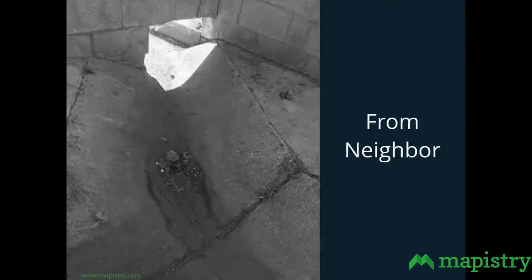Another big one is your neighbor. Who's contributing to your own TSS? Do you have a swale or a curb cut or some sort of drain that's coming onto your site that's contributing TSS to your own problem? Unfortunately, once it's on your site, it's your problem to deal with. There's not really a way to get out of it without going through some hassles.